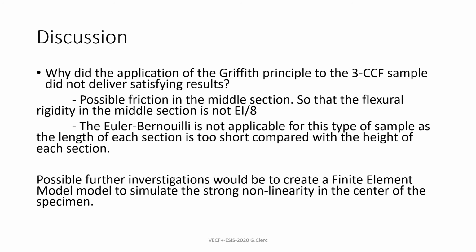The second point is that the Euler-Bernoulli equation is probably not really suited for this type of sample. Indeed, the Euler-Bernoulli equation is correct for long beams which are not so high. And in this case, if we consider each section, we have short sections which are quite high.